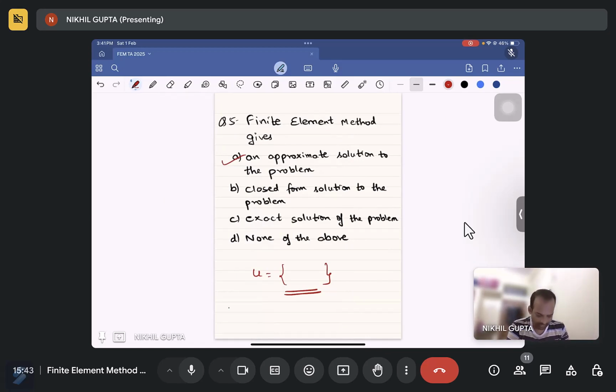I have one doubt here. I was seeing in the lecture that when we were formulating any equation for the beam or bar element, we were always defining the range for x, like from 0 to L, or 0 to 1. So isn't it a closed form? No. Closed form is related to the solution you are getting. Your solution should give the exact solution at every position. The one point value, it doesn't give.